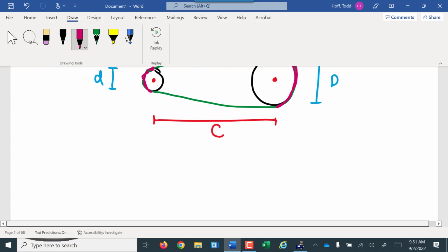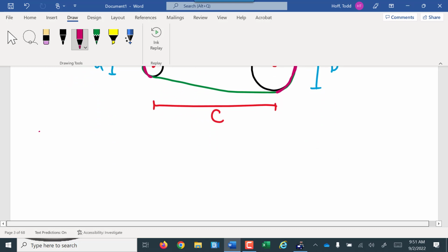So one of the parts of your formula is the portion of the belt that's in contact with the pulley. That's just the 1.57 times each diameter. So what they do is this. They add the two diameters, the big diameter and little diameter together, and multiply by the 1.57. That is the combined distance that's in contact with the two pulleys.